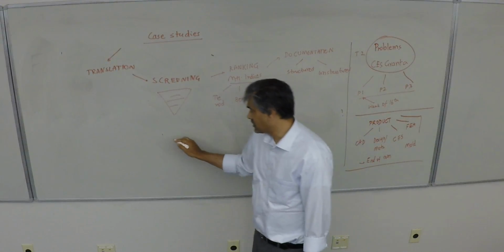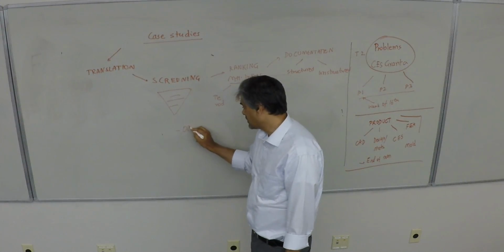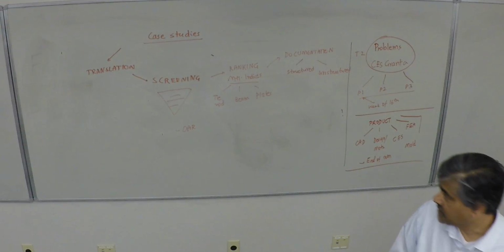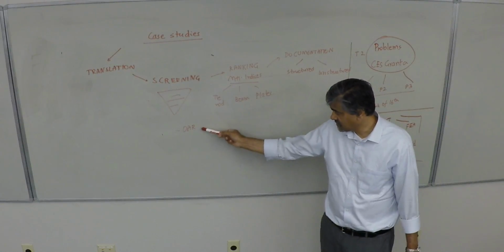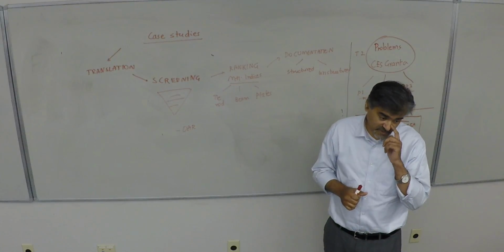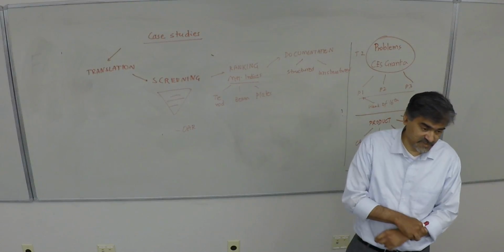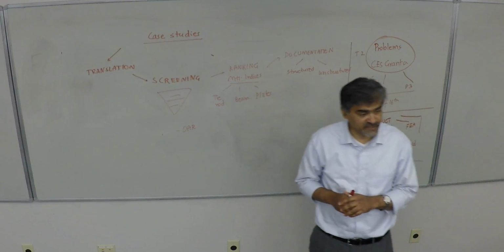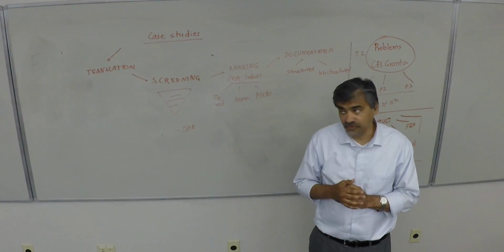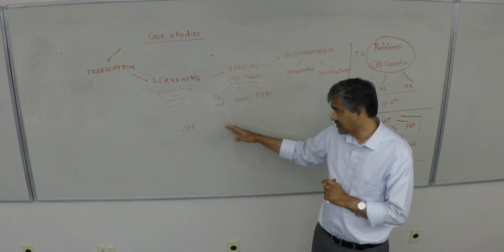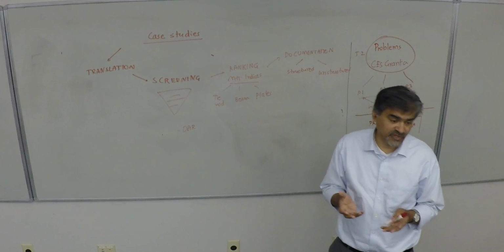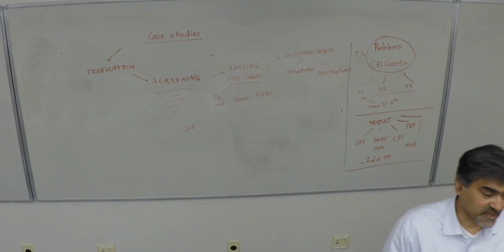The last time we took a case of an oar used in rowing or canoeing applications, and we went through understanding the translation. From this, we saw the narrowing down by plotting modulus versus density, I believe, and from that we down-selected specific materials and ranked them. Although 4 or 5 things would work, we saw there was a brittle failure if you used a ceramic, so we discounted that and came down to 2 choices: wood and CFRP, carbon fiber composites.